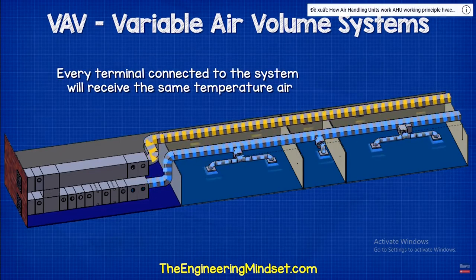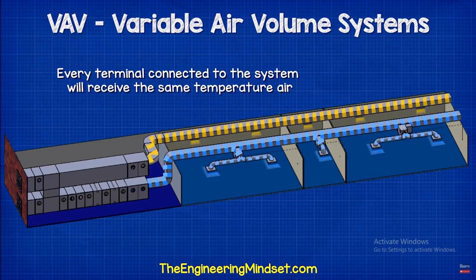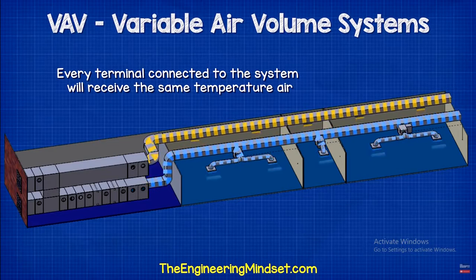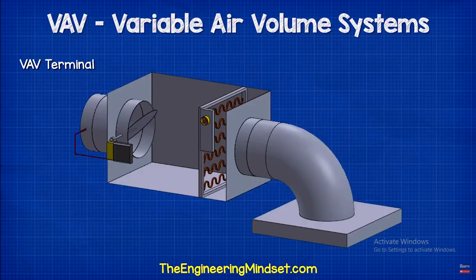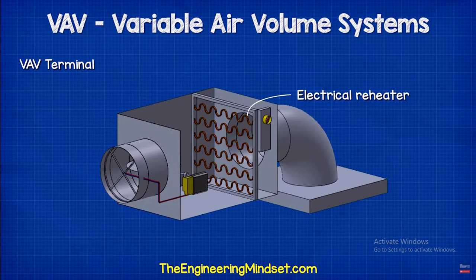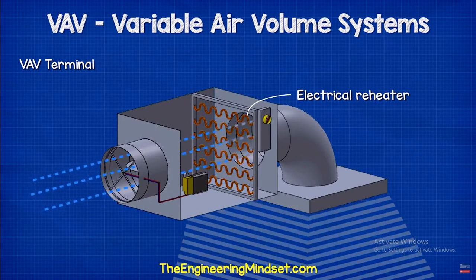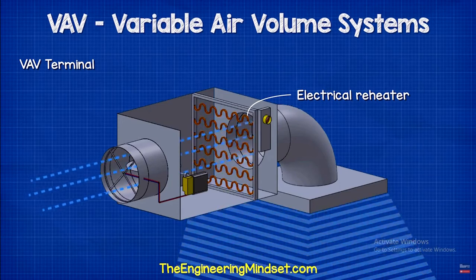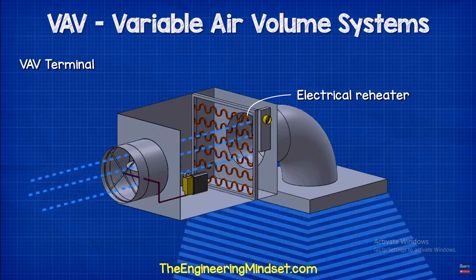These then connect onto this cross shape. The cross shape is an airflow sensor, and it is basically measuring the change in pressure across the inlet. There will be a difference in air velocity between the center and outer regions of the inlet duct, because air flows faster in the center.